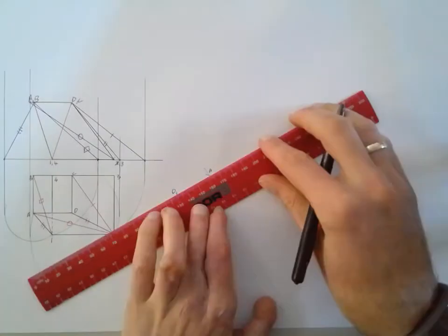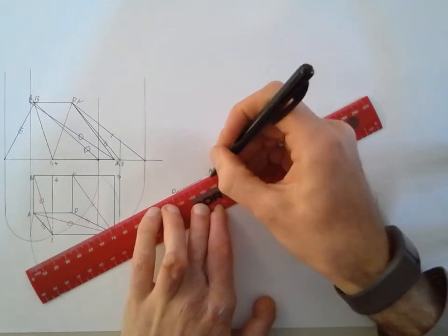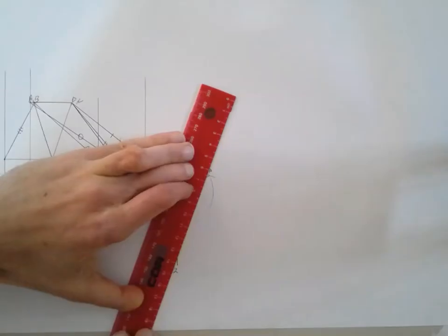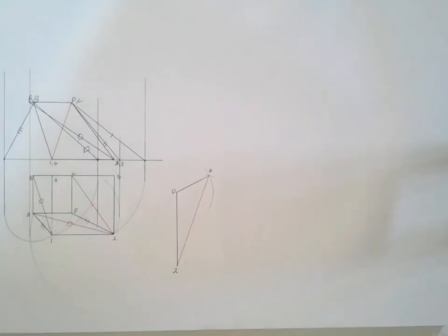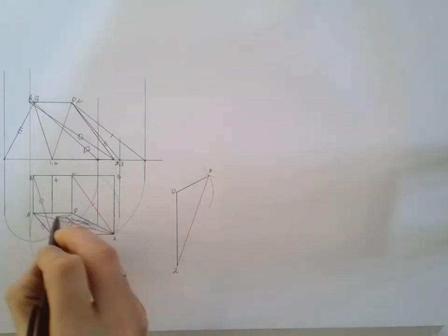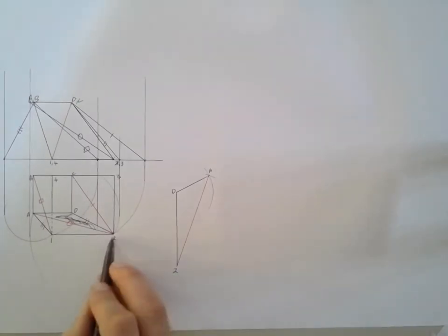If I join those 2 up with the dark line, and then the joining line between point A and point 2 must be drawn as a construction line, because it is a line that you created to be able to triangulate. So line A2 is construction. Then we've now completed that triangle, so we're going to move on to the next triangle down here, and we need the length of line 2-1 or 1-2.